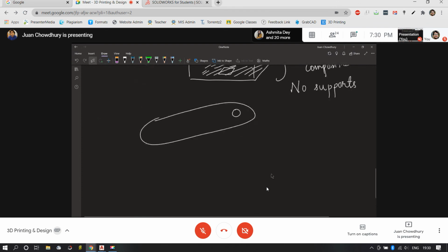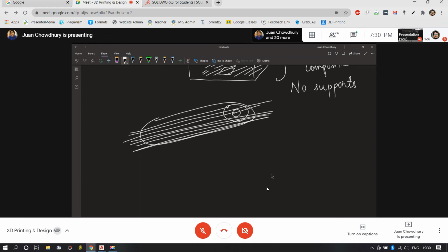More so if you remember that robot that we were building, it had a screw in between, if you remember, in the hole, which was larger. So if it starts printing layer-wise, it will not create any supports in between over here. It will just fill it up with powder. And after it has printed all of it, if you remove this part, you can just empty the powder and this part will be free to move.